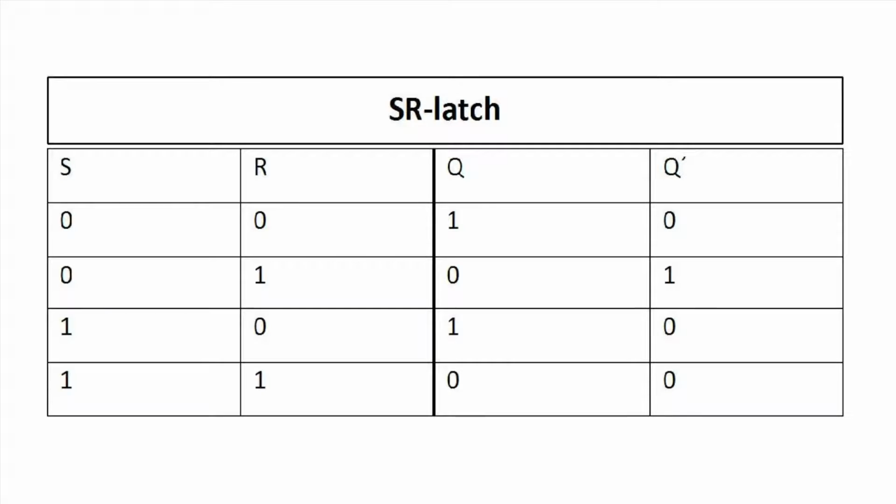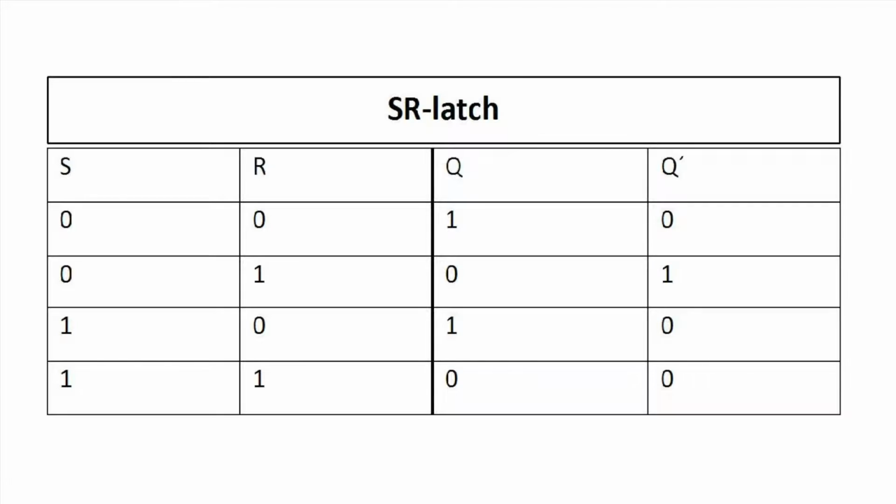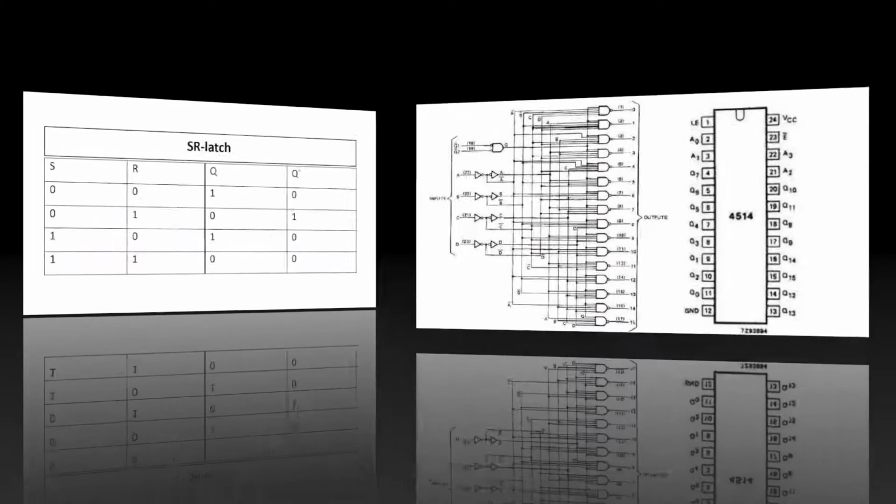When neither of the buttons was pushed, the Q light got lit. It is completely random which light gets lit in the beginning when we turn on the board. When we reset a flip-flop, the not Q light goes high. When we set a flip-flop, the Q light goes high. When both buttons are pushed, we are setting and resetting at the same time, which can't give positive output, so both Q and not Q were negative.